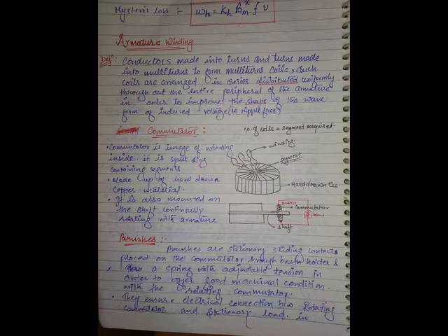Now, mechanical conditions are very simple. If the brushes are tightly held on the commutator, there is friction, there is a temperature rise, and there is a chance of sparking. If the brushes are loosely held on the commutator, there will be an air gap. Since you can't expect a perfectly smooth commutator surface, there will be small fine variations. So the brushes are placed on the commutator with a spring. A spring offers some flexibility and tension. So by adjusting the spring tension, you can make the brushes rest on the commutator with proper mechanical conditions.